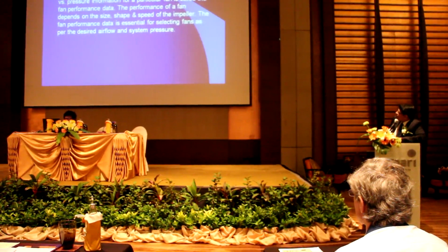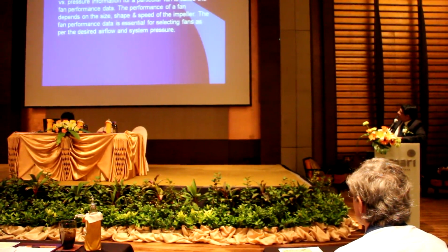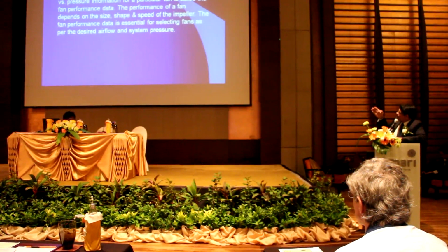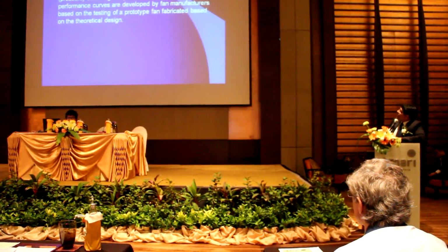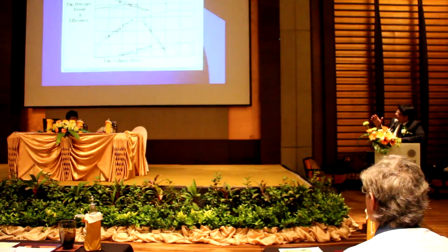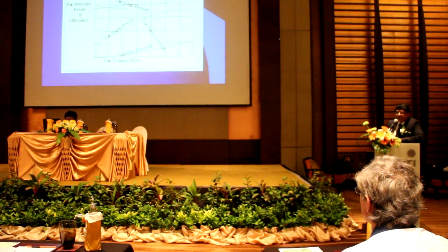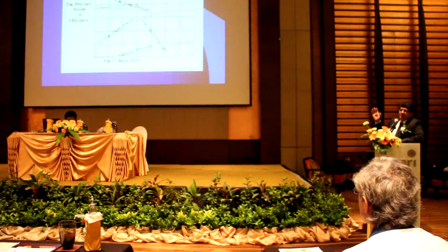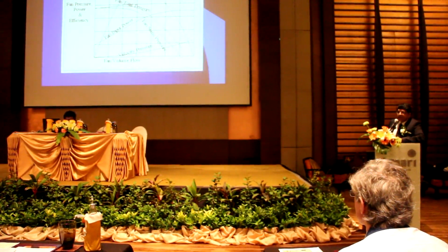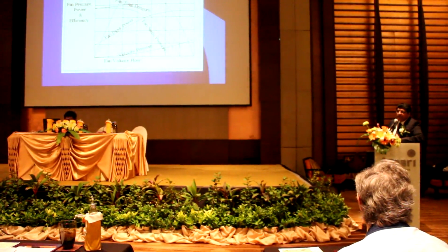The fan performance obviously depends on the size, shape and speed of the impeller, and it is essential to get the proper desired airflow and system pressure. You will have to go into this. For any fan that you want to check, we talk in terms of fan characteristic curve. Without this characteristic curve, you won't be able to really choose the proper fan for your application.